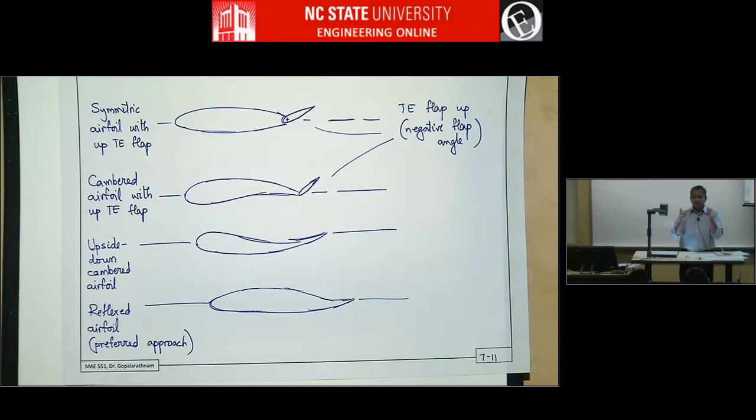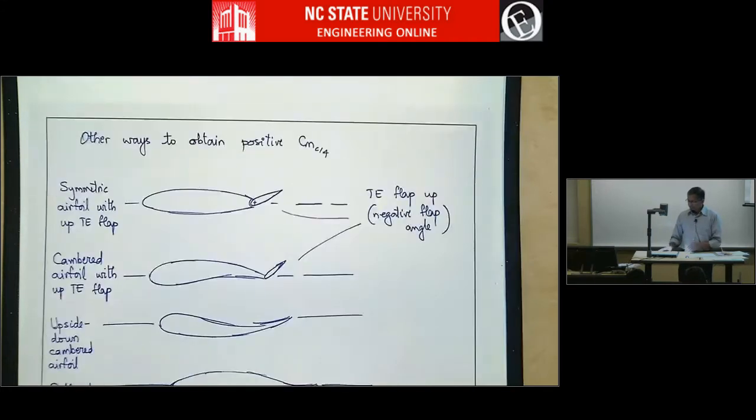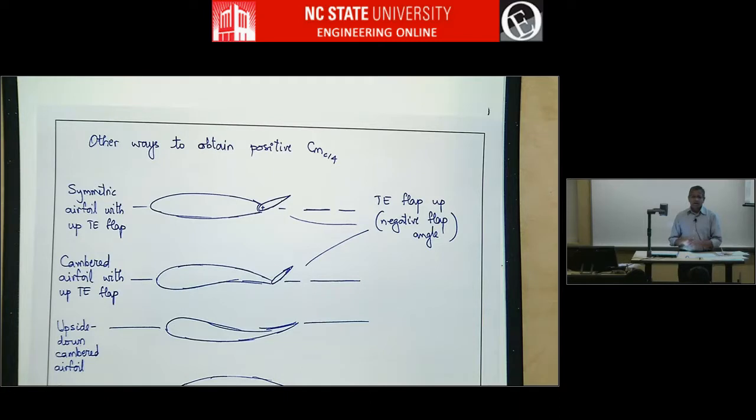So it's a regular cambered airfoil. He turned it upside down, it became this. Now he's got equilibrium, because you have to have positive C_M at c/4 for equilibrium. And even if it's not stable, it was just for a short flight. It was coming down to be a controlled crash, and he was able to do that. It's just cool that he did something instinctively and got it down, whereas normally this thing would have been a total wreck.